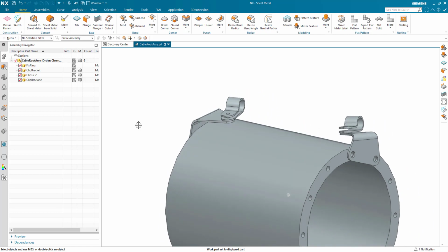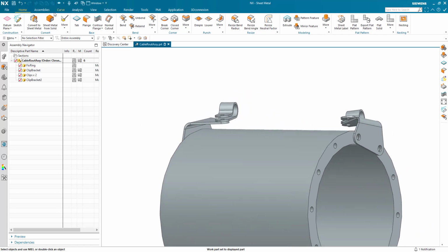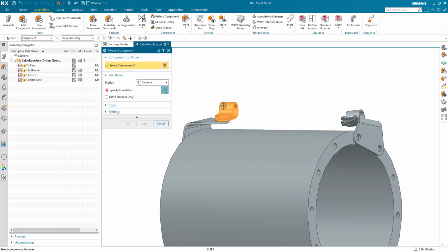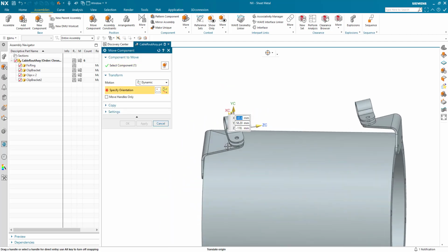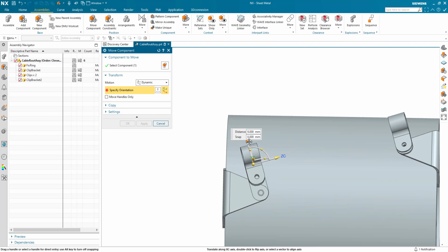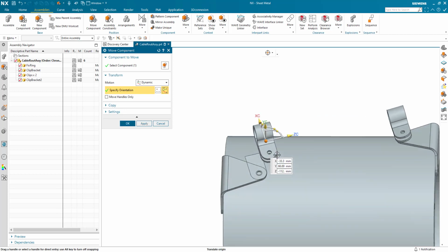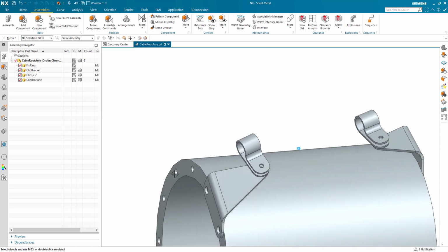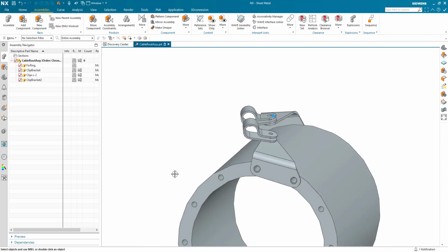And then we have the brackets created for the clips, and of course, just as I did with the other one, I can move this one and the bracket will update accordingly, irrespective of how I move this around. Okay, multi-bend tab.